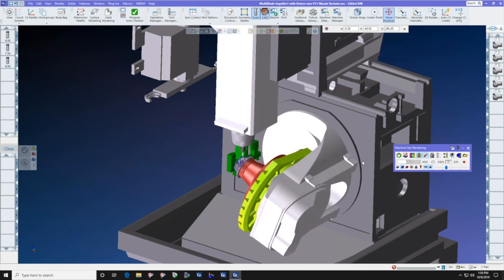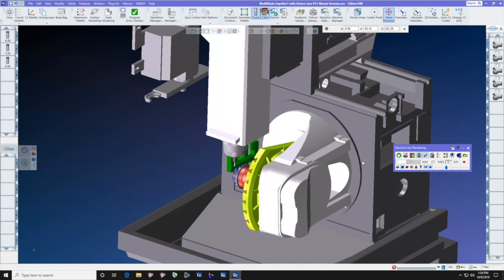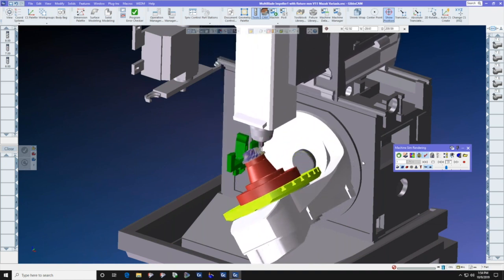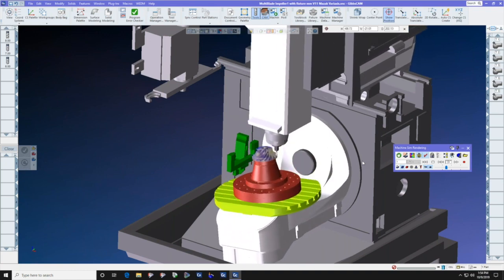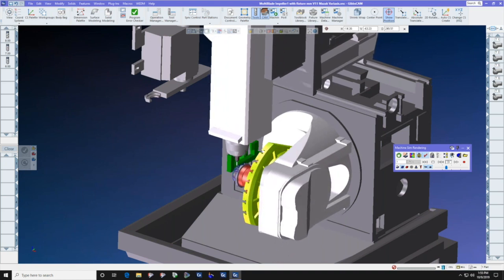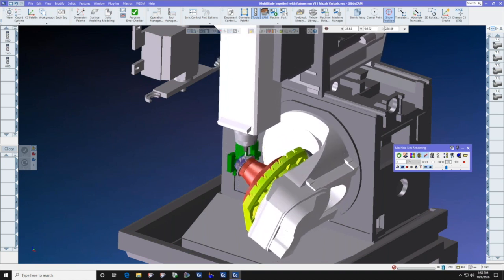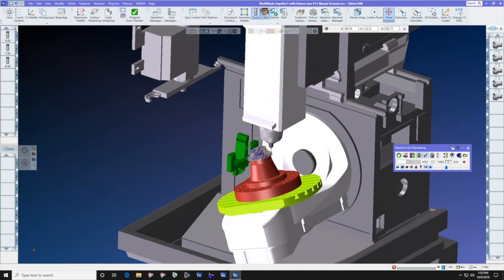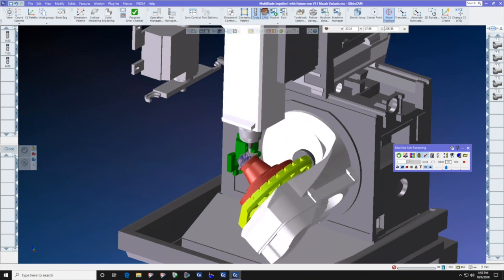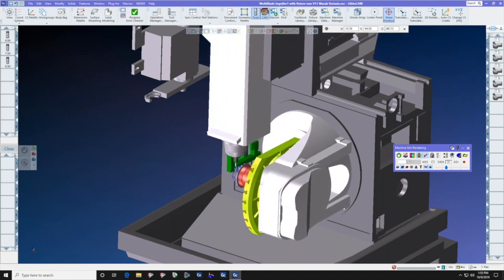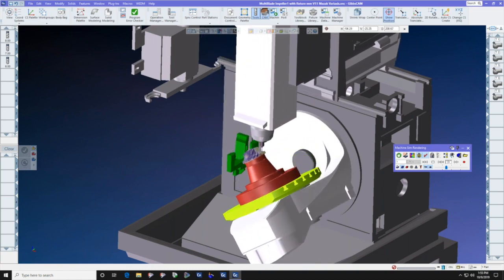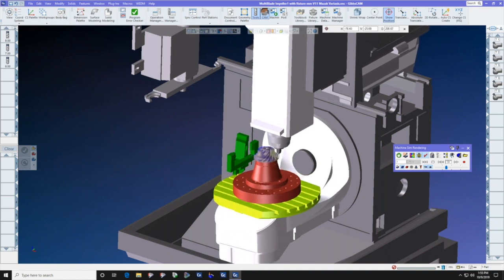The next level is exactly what Patrick showed you today, and that is 2.5D. 2.5D solids is just a fancy way of saying prismatic parts. Okay, flat walls, vertical walls, round holes that go through it vertically. With 2.5D solids, you can not only read in a part in many different solids, you can access, you can touch that solid. You can do things to it like Patrick showed you. You can click on faces and move it into position.